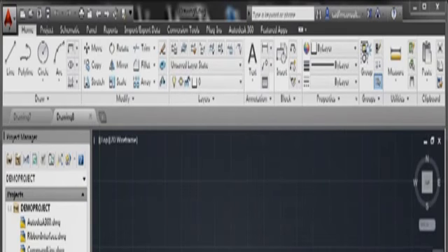Click on open. That opens up a blank new drawing. You saw it flicker slightly there. It's opening up a new DWG, which AutoCAD sequentially is called Drawing 8 DWG. Now, take the crosshair to the center of the screen and just type the word startup, all one word. Because we have dynamic input switched on, as you can see, it all comes up next to the crosshair there. Select startup on the menu that appears.